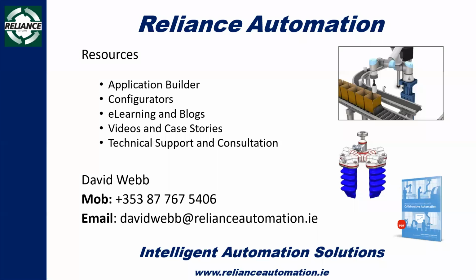So Universal Robots have an application builder. And although this is primarily designed for the actual programming of the robot itself, what it's really, really good at is taking you through step by step on several different types of applications. So whether that be palletizing or CNC or machine tending, it actually walks you through every step and provides good explanations about the different types of grippers to help you select which one would be best for your application. And that ties in with the whole UR Plus and UR CAPS infrastructure that they've got available.